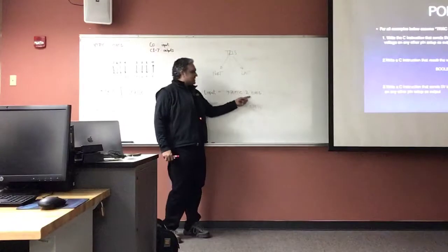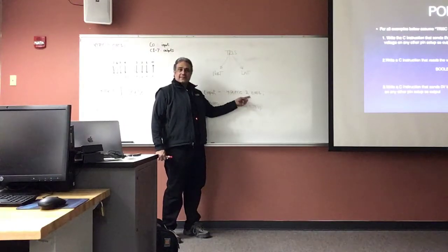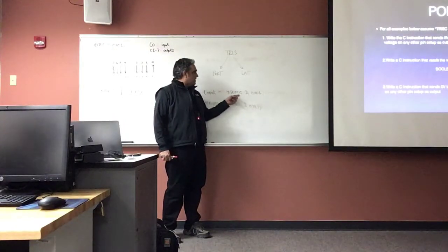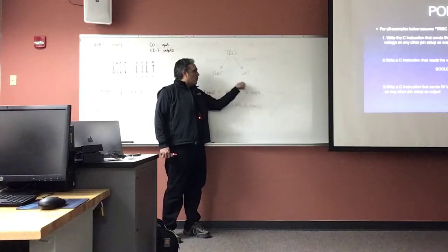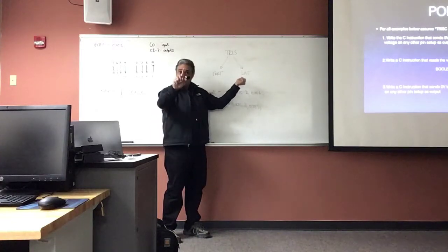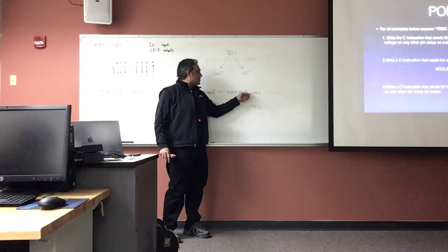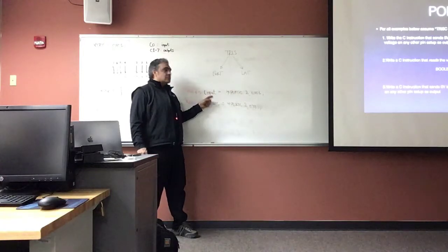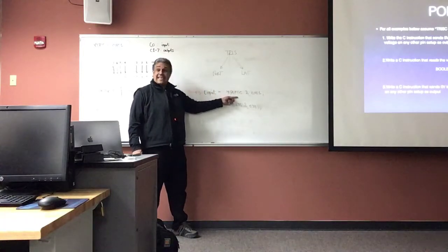Because the AND gate destroys data. I'm going to grab data, I'm going to AND gate it with that. Whatever effect happened, listen to what I'm going to say. Whatever effect happened on this instruction, I am sending it somewhere else. So port C remains unchanged. It's not saved yet.